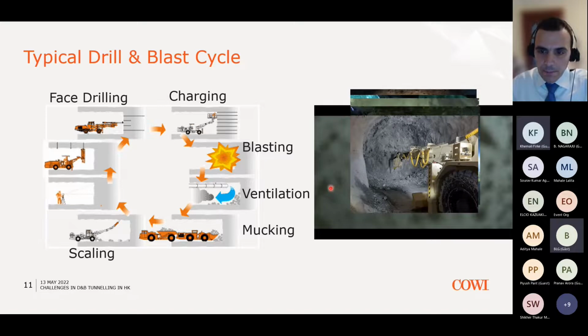The next part of the cycle is to do the scaling, so you need to make sure that you remove any loose blocks that may fall prior to installing the support, and therefore, for health and safety reasons, you need to do that. As you notice from this photo, this is done from a distance, so you are not supposed to do this in an area where the support has not been installed.